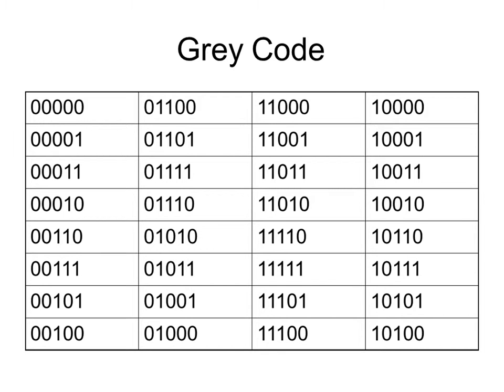Let's go from a 5 back to a 4. We still only have a 1-bit change. So no matter what direction we go in, when we're counting with the Gray code, we only have a 1-bit change. So we only have one propagation delay every time. The propagation delay on every count would be what? Would be the same. Does that make sense? Yes or no?